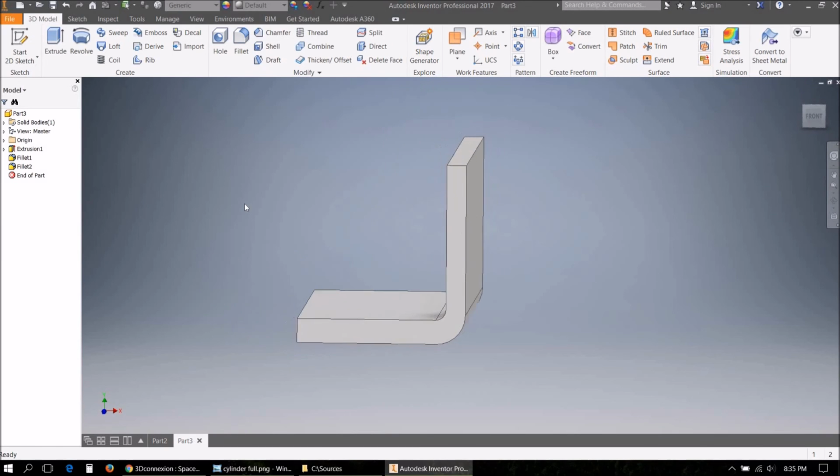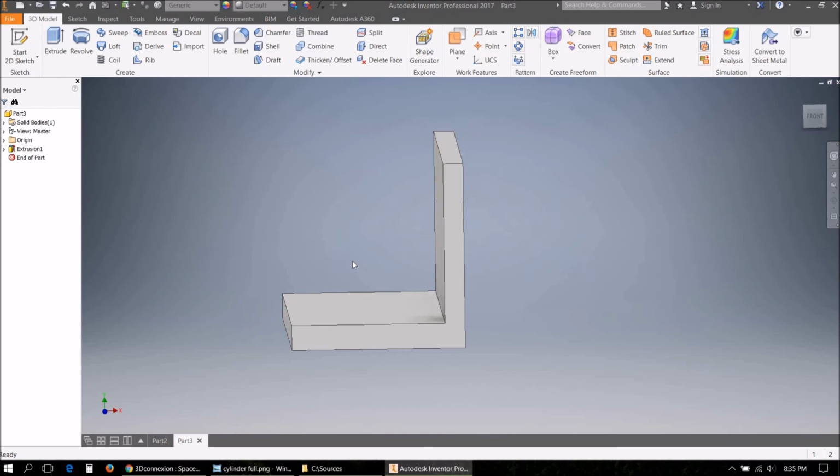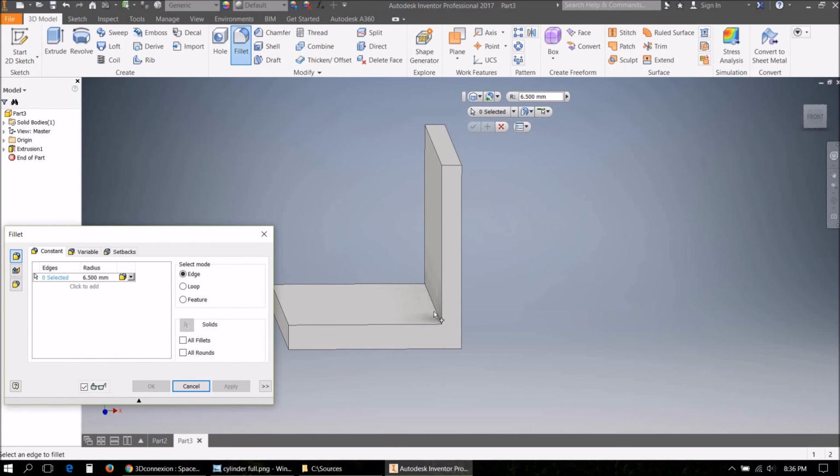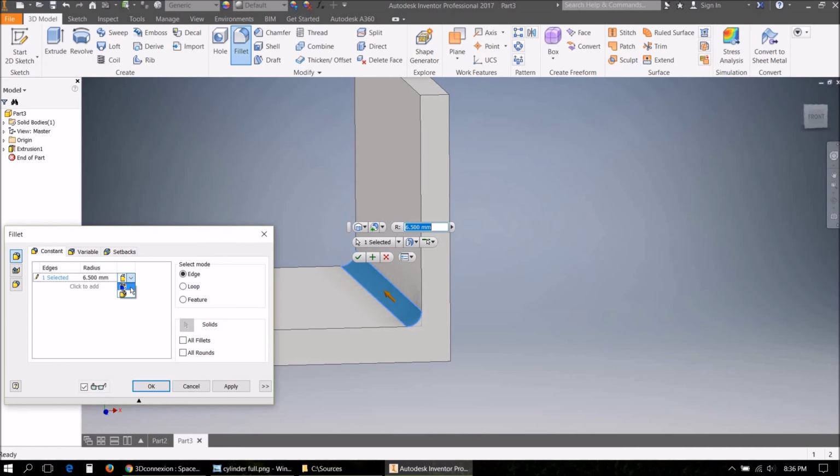You see? So basically this looks the same as a bend part, but now if you want to create a low resolution model later on, you just delete these fillets in the feature tree, and then it can be replaced with a normal map. The other thing is when you do add fillets, then if you can, then you should select the G2 fillet right there.